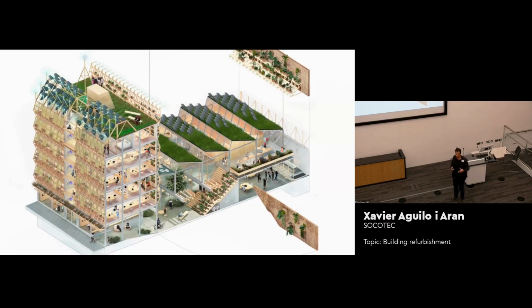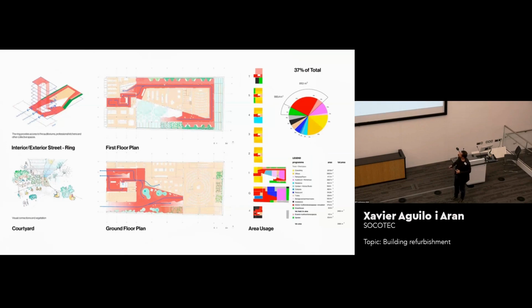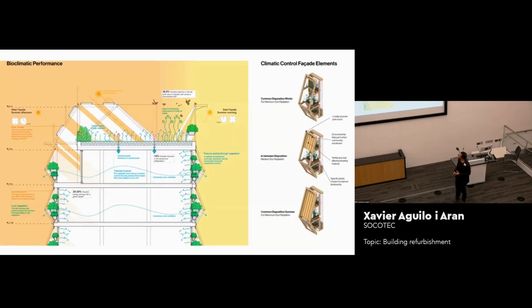And honestly, we didn't know how that was standing up there because it was relying only on the brick walls, okay? So we did a lot of approach in terms of design, in terms of reducing the impact of the building and how we can do refurbishment. At the end, what we decided was to play with this kind of solar protections, having the radiant floors. So what we did was to increase a little bit the screed of the radiant floor and put cold water or hot water connected to a geothermal energy on the ground, on the warehouse part.